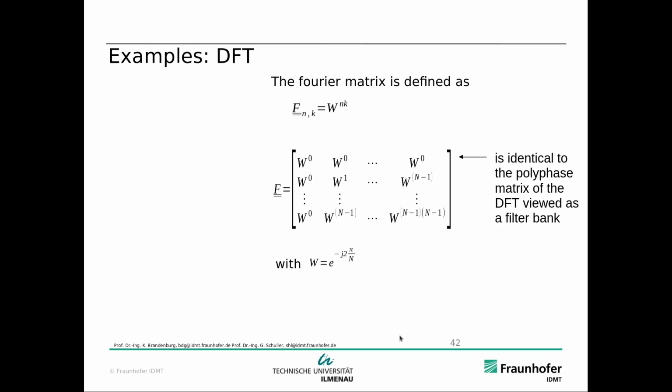So we can actually analyze it. Here you can see the resulting polyphase matrix, which just contains these values here. You can see the W is e to the j 2 pi over N, and here you get those different exponents, like in the kernel. So this is our DFT transform matrix, which is identical to our polyphase matrix, and there's no z in it. It's just complex numbers which are easily inverted, in this case by the inverse DFT, which is doing exactly the inverse.